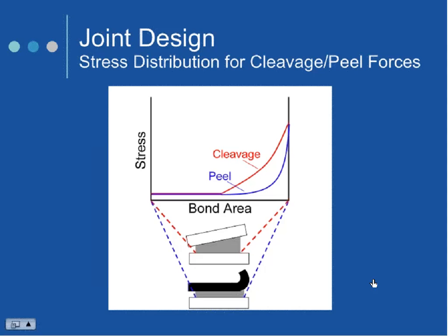Now, that said, I know of many, many applications where we're bonding balloons on catheters, and one of the tests they do is to inflate it upwards of 50 times, and that's putting an extreme peel force on the balloon. And they give it 110 psi, and it actually withstands that quite nicely, and the substrate fails before the adhesive does. So again, it's starting with a nice, strong bond, good substrates that are good to bond to, and really designing right for the adhesive in the first place. You can do it.